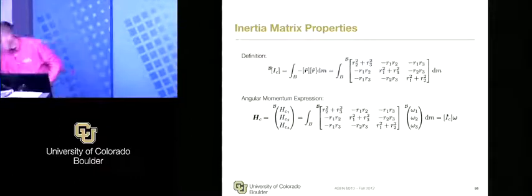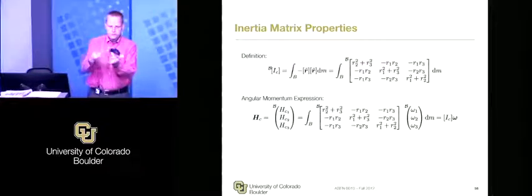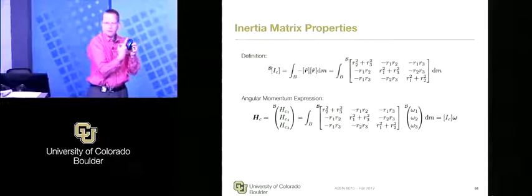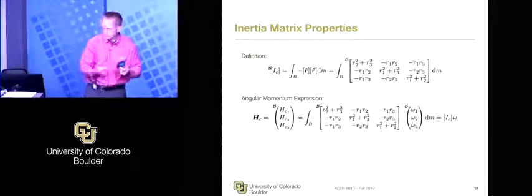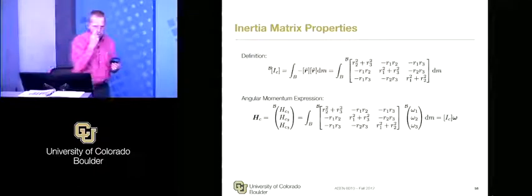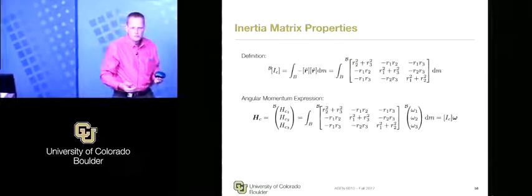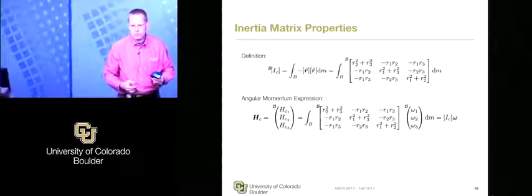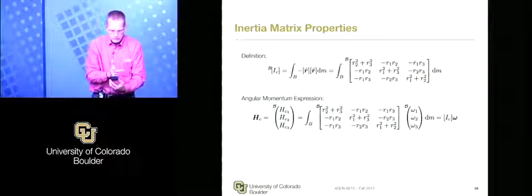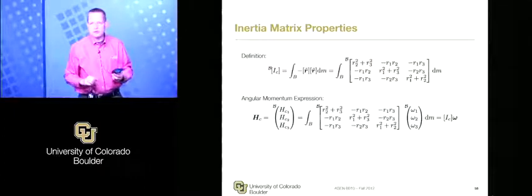So if I'm looking at an object like this, it's got 3 distinct dimensions, and the principal axes would essentially be your symmetry axes. That's what the book gives you. Are the inertias that you get out of the book typically 9 elements, or are there fewer elements that they give you? Franklin, what do you think? If you are on principal axes, it will only be 3. Yeah, they will only give you the 3 diagonal elements. So if you line up like this, then your inertia tensor just becomes a diagonal matrix, which is nice and simple.